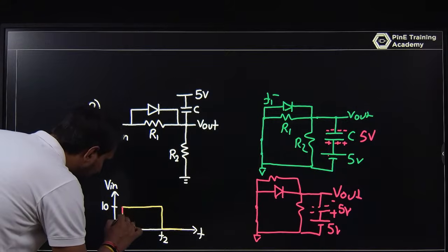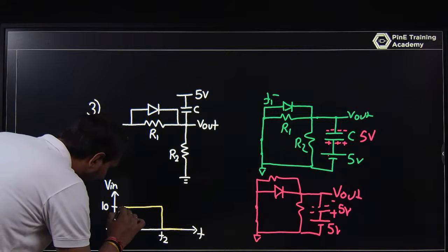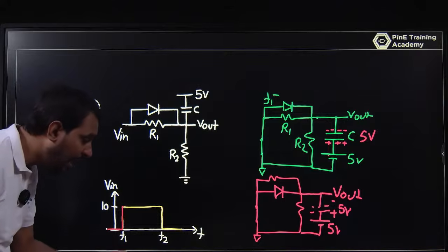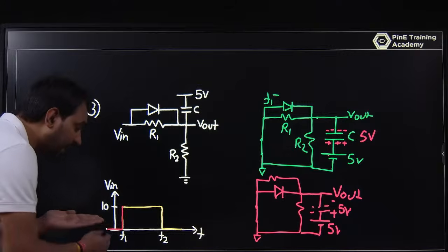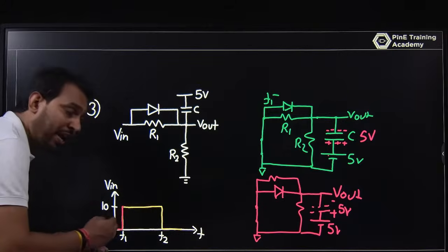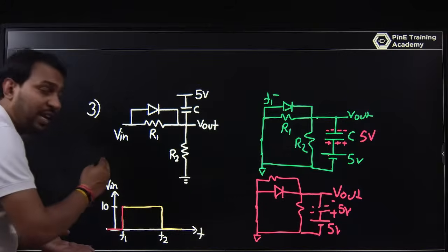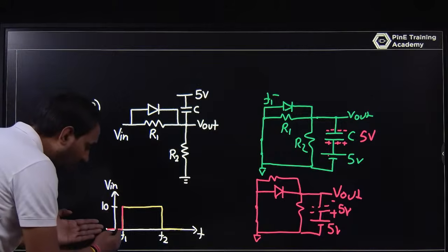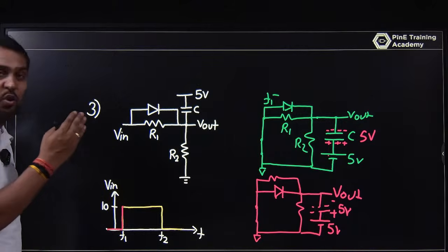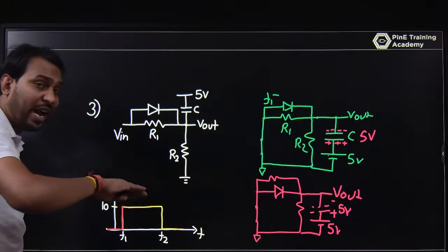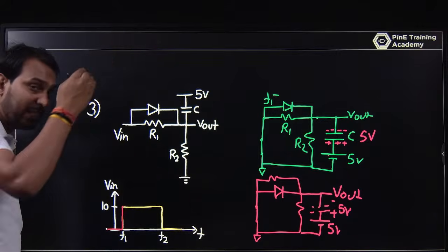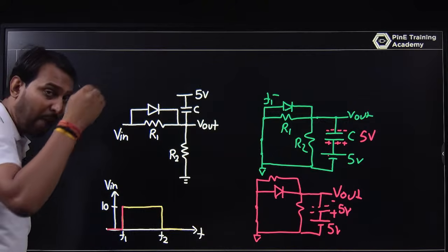That has a sudden change there. That is a very important point. The capacitor has a voltage of 5, and because the diode is a short circuit, there is no charging time. It charges suddenly, so the output suddenly reaches 10 volt, and Vout is opposite the direction of charging and it is maintained at plus 5 from the upper side.